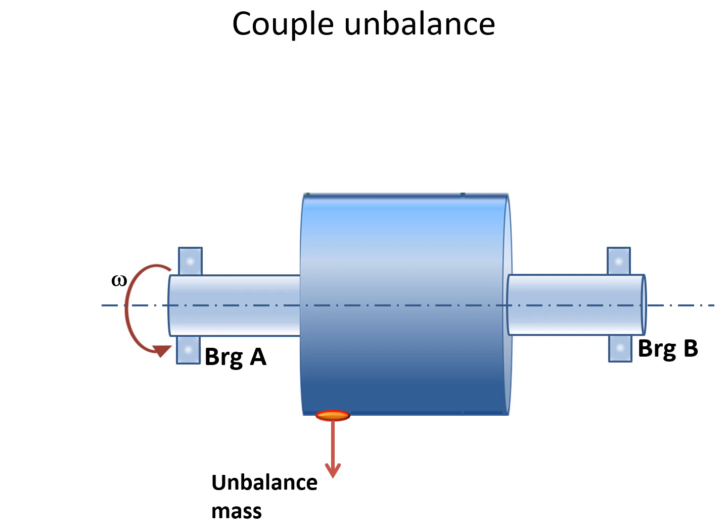For simplicity, we'll first understand taking one mass. Let us consider that there is one unbalanced mass on a rotor. Let us say this rotor is turning with some speed and the rotor is supported on two bearings. Let us assume that we have provided one balancing mass on the opposite end exactly at 180 degrees. Then it can be balanced.